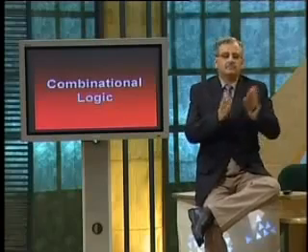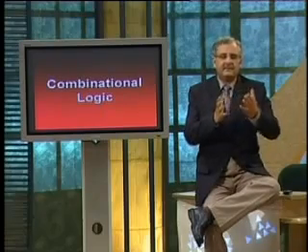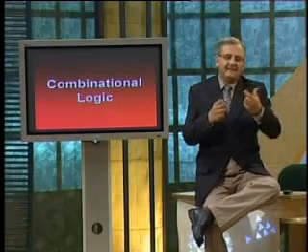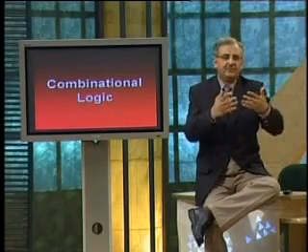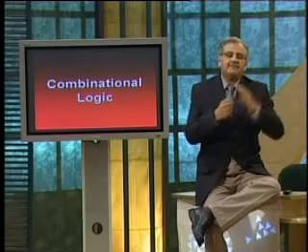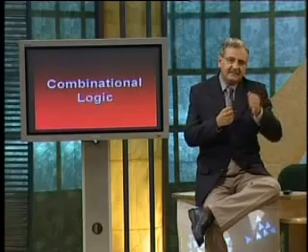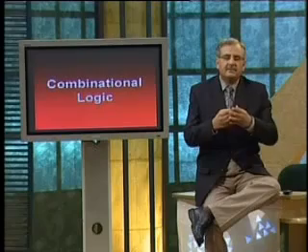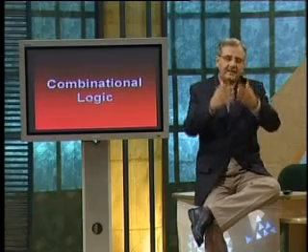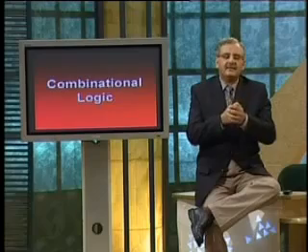So, basically, implementing a sum of product expression using logic gates, you would have a circuit having three levels of gates. The first level of gates would have the OR gate, which basically sums up all the product terms. The second level would be comprising of all the AND gates, which generate the product terms. The third level of gates would comprise of the inverters, the NOT gates, which complement the different variables and provide them as an input to the AND gates. So three levels of gates.